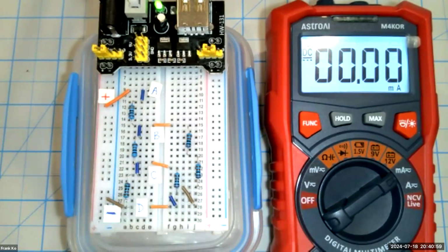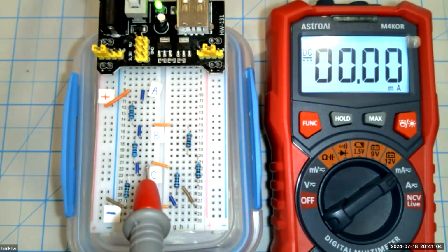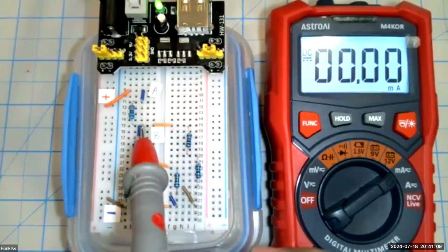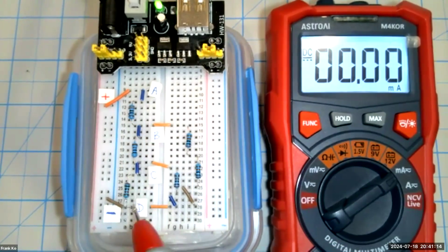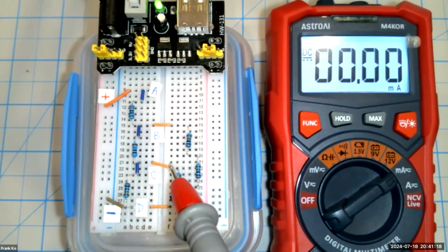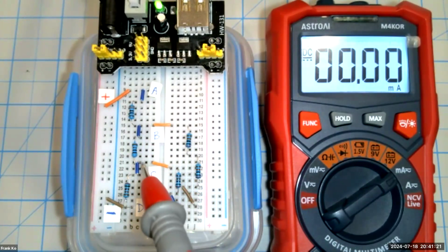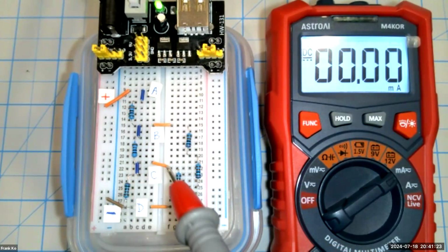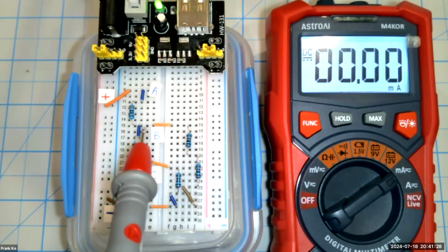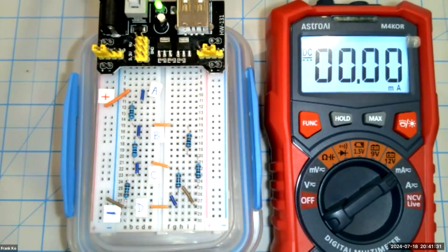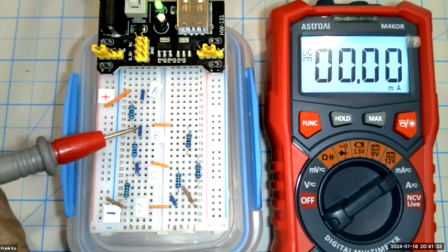Now, the current through R2, take a look at R2. R2 is between point C, right here is point C, and between point B. So between B and C, according to our schematic, we had 1 milliamp coming up through R3. We had another 1 milliamp coming up through R4. Don't these two currents combine at node C? 1 milliamp plus this 1 milliamp combined at node C to give us 2 milliamps that's supposed to flow up through R2. So I happen to have a convenient jumper already built in right there.